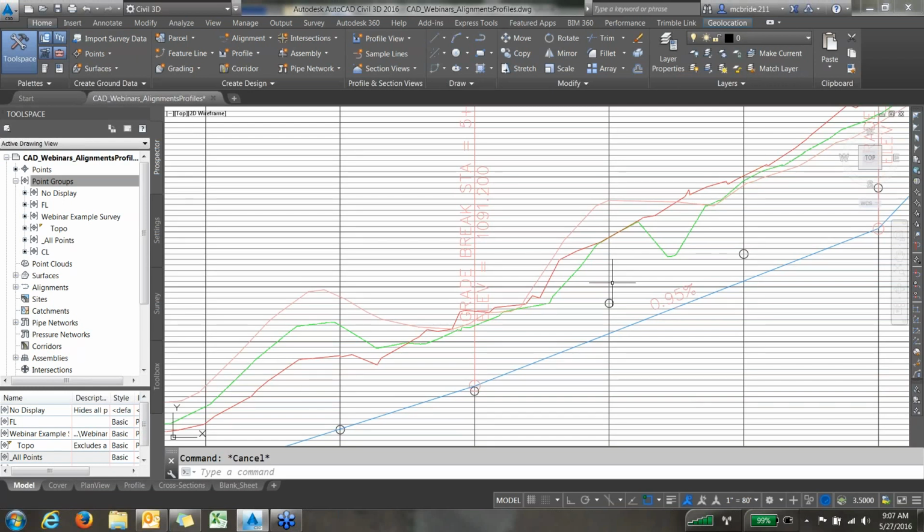So you want to keep your banks at the same elevation as the current ground level. That's why you're using these two bank offsets to judge: am I 1.5 foot below these two banks? If I am, then I can just daylight the sides of my grass waterway and all the surface water will flow into it. So that's important.